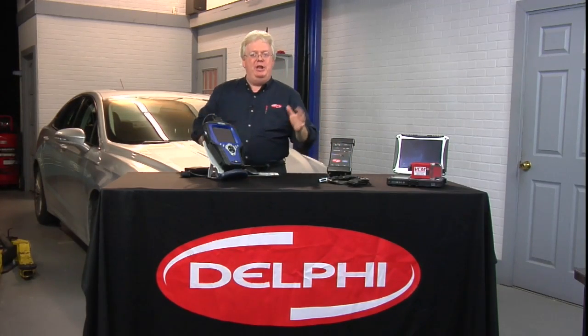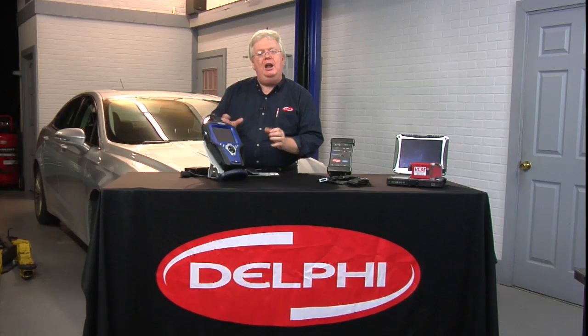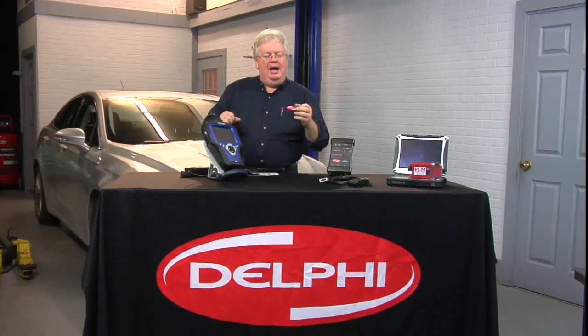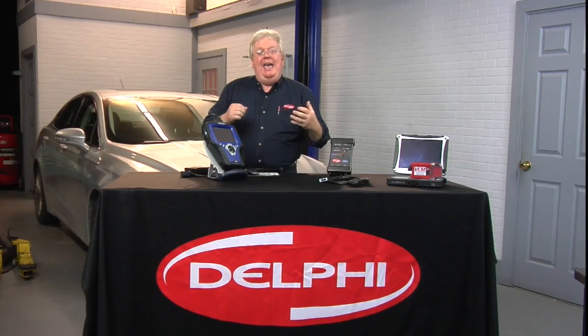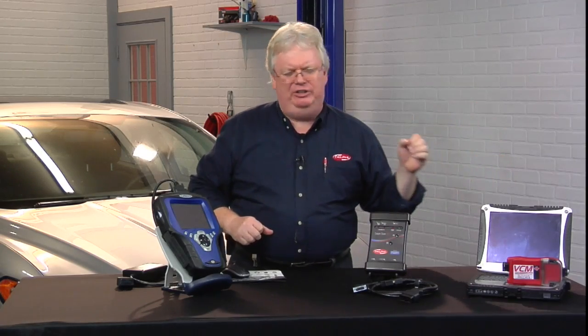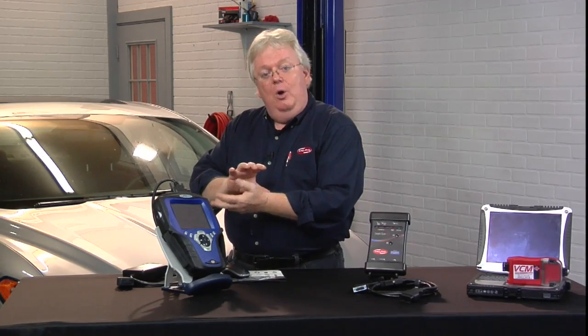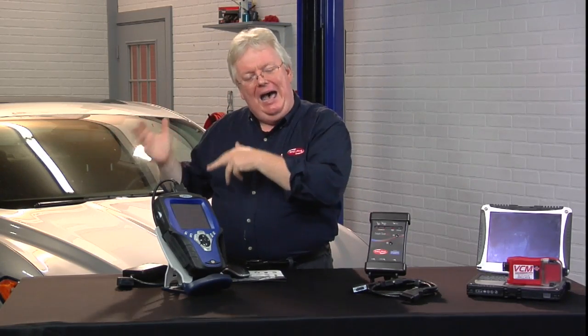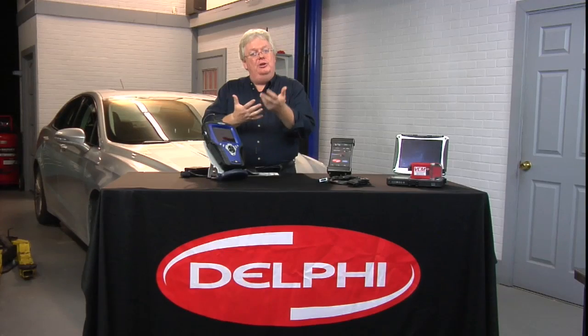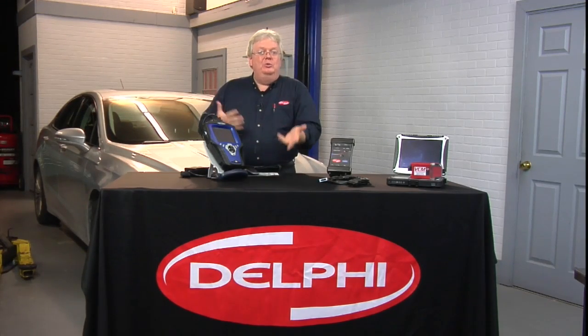And of course, I'm going to be partial to this one, because it's got our name on it. But seriously, it's a good tool, but there's a lot of good scanners out there. I would never have just one scanner in my shop. I would have a collection of scanners I prefer that are OE level, that work on a lot of different cars. And for cars I see a lot of, if I have a ton of Ford customers, I'm going to have an IDS. If I have a ton of GM customers, I'm going to have a Tech 2, or maybe even a GDI or MDI, which is able with the right software subscription to do Tech 2 emulation, so you don't need it for the older cars. The MDI does the newer GM and the older. So as the business case provided for your particular situation, add tools as you go.